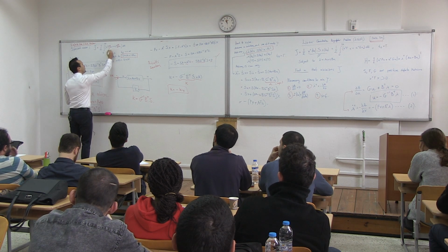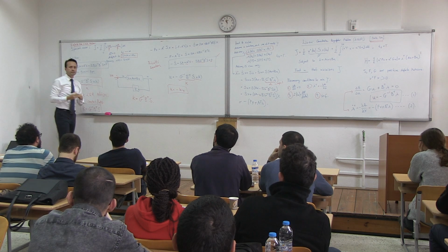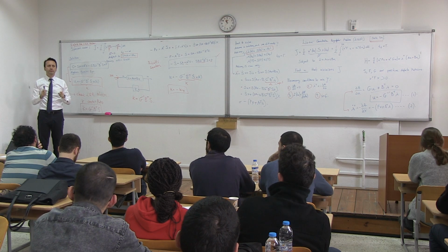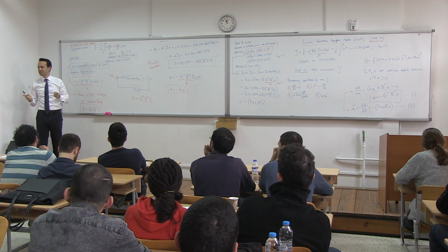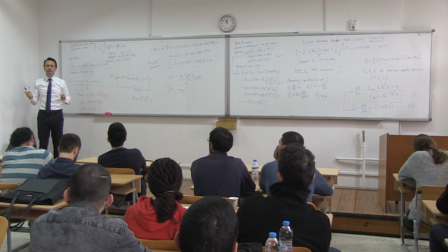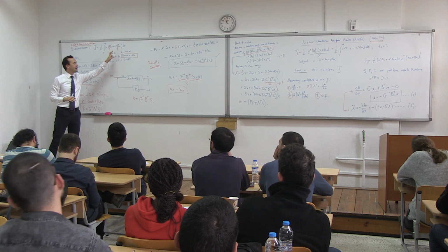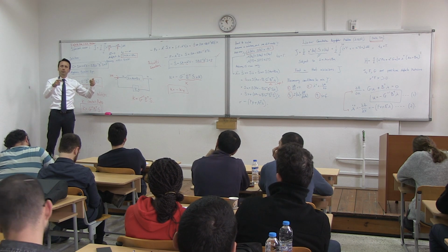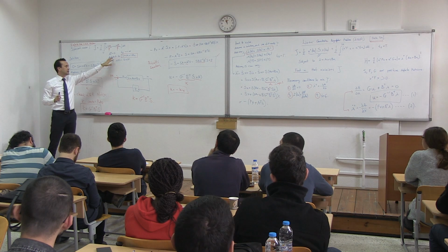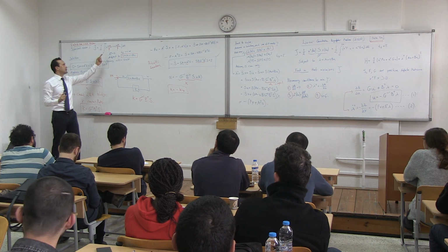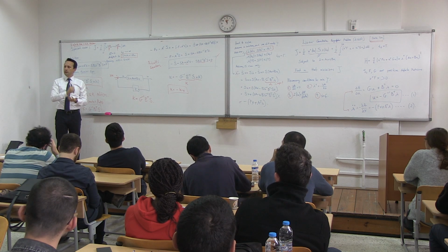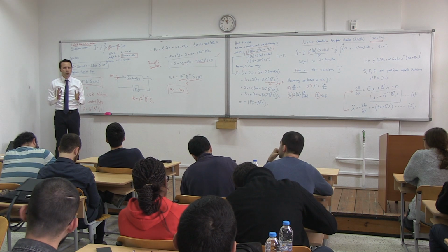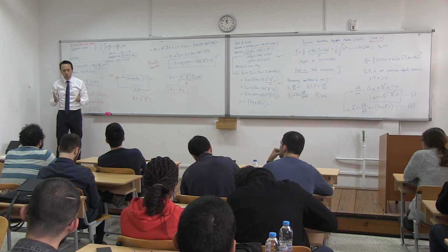So question is now, who is going to give me F and G? Well, that's the job of the designer. You are going to choose F and G. Nobody's going to give you F and G. Okay? You are going to choose F and G. So the problem only needs F and G to solve because A and B come from your dynamic system. It's still the linearization of the dynamic problem around an equilibrium point and all that. So this is given. What you need to choose is F and G. Question is, how do you choose F and G? Okay? And this is the job of the control engineer, to choose F and G in a meaningful way.